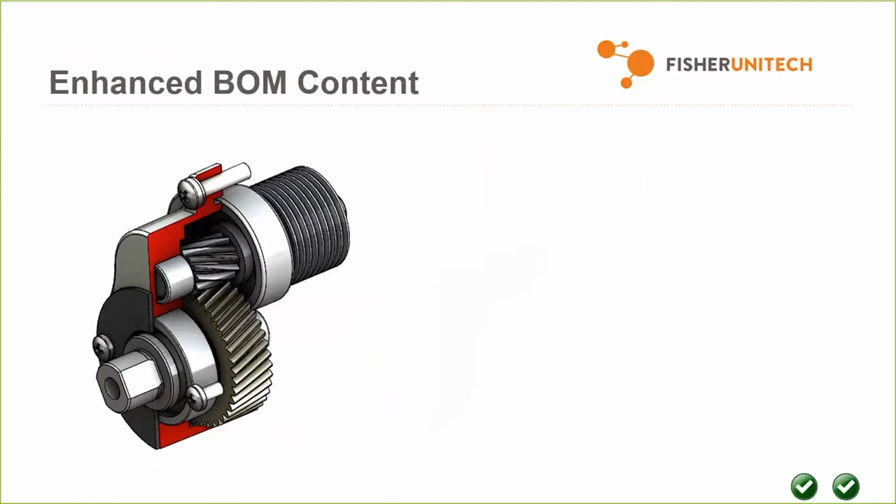Because PDM's goal is to export the bill of material upon approval to the next system in line, ERP system, MRP system. There is decidedly a breaking point between a manufacturing bill of materials and an engineering bill of materials, but we can enhance the content of the engineering bill of materials right inside of PDM, so when it gets handed off, it is that much more complete.